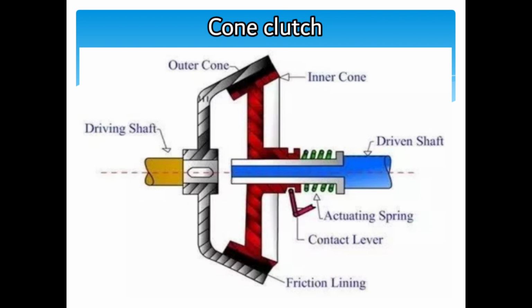Cone clutch applications include synchromesh gearboxes, which synchronize the drive and driven shaft speed to enable smooth engagement between transmission gears. The cap components connect rigidly to the drive shaft, spinning with it as a unit.